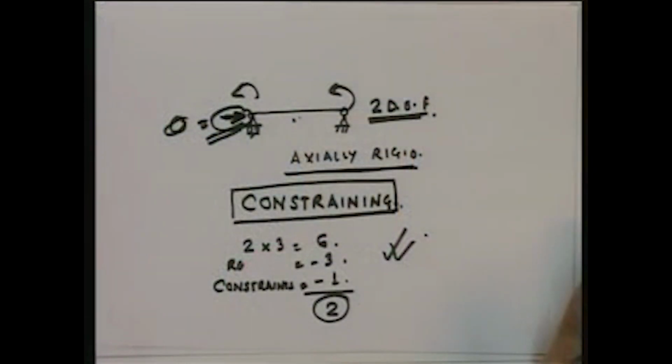Then find out the restraints. What are the restraints? The supports. The restraints are provided always by supports. So you go to every support and find out what kind of restraint it gives. Add up all the restraints from all the supports. Okay, those are the total number of restraints. Those are to be subtracted from the unrestrained degrees of freedom.